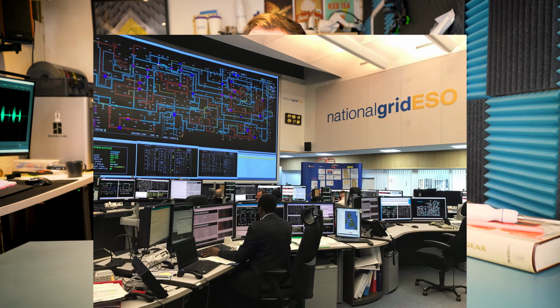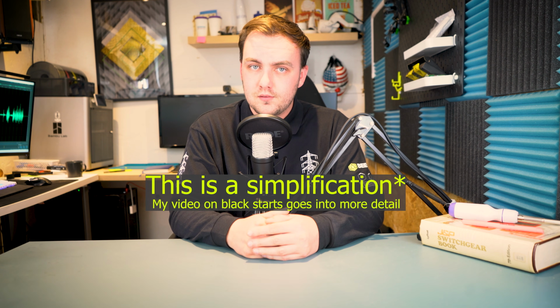Grid-connected equipment like generators, motors and transformers rely on synchronization with the grid. If you want to know more about what we do when we have a blackout, check out my video up here. Frequency is closely monitored at the network control center, so that frequency can be controlled either by using up excess energy on energy storage, providing energy at a reduced price to higher load customers to encourage them to use it, or selling it via interconnectors.